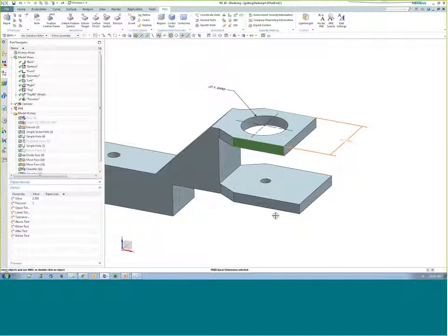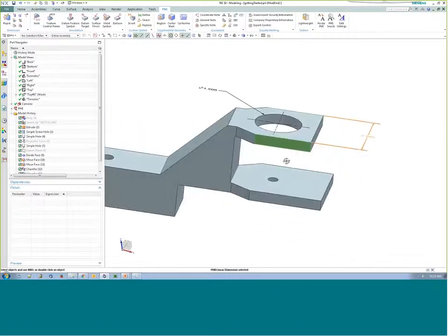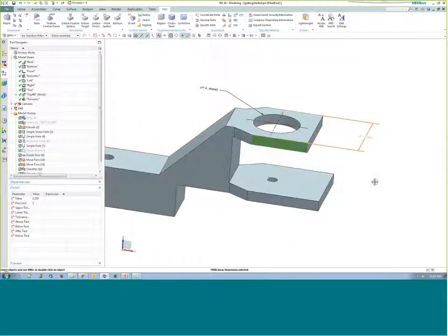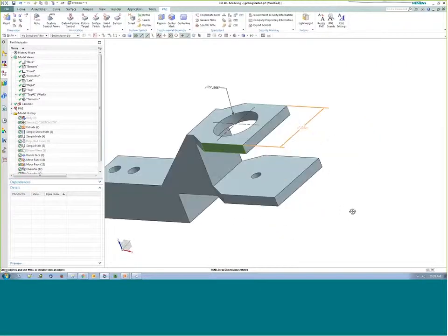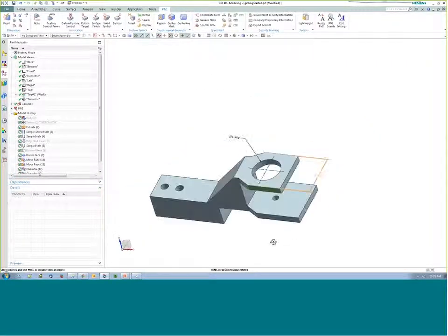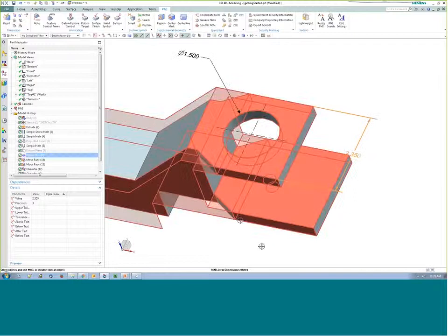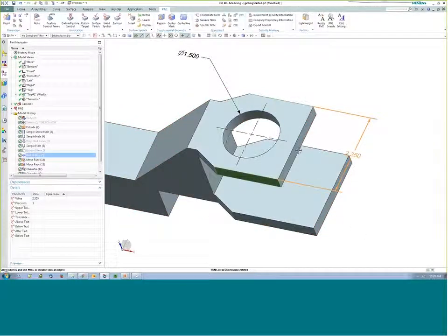When you're doing a 2D model, you don't really get that distinction because you can't see into the plane of the part. It selects the edge or whatever it is that you dimension off of in the 2D part, and you don't really know which face it's associated with. So the standards require that you can select and highlight objects that you want that dimension to be associated with.